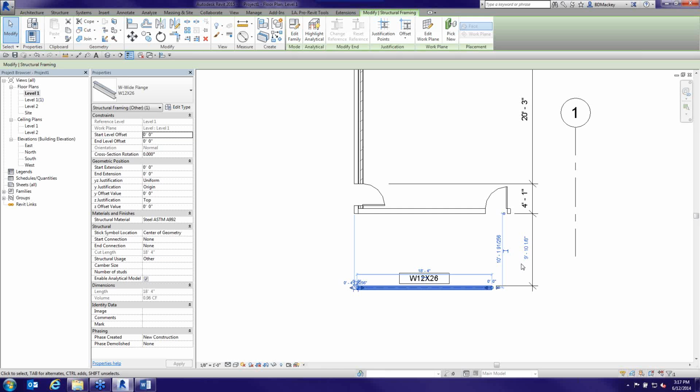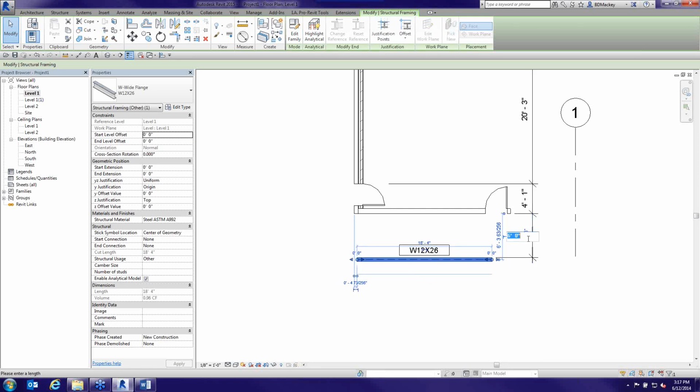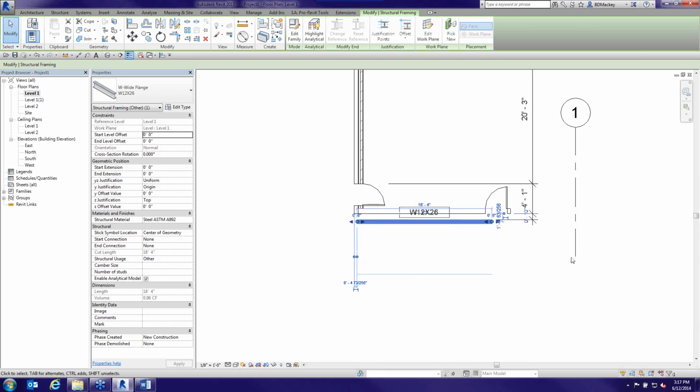So if you're dealing with metric files, instead of CFM, you can type in what it needs to be, and Revit will understand that. So you're not set to only the units you have set up. You're set to be able to type in anything. I could go say, hey, I wanted 254 millimeters and get my 10-inch equivalent. Liters per second. Thank you, Ray. So I could have typed in on a diffuser LPS as opposed to CFM when I'm doing this.